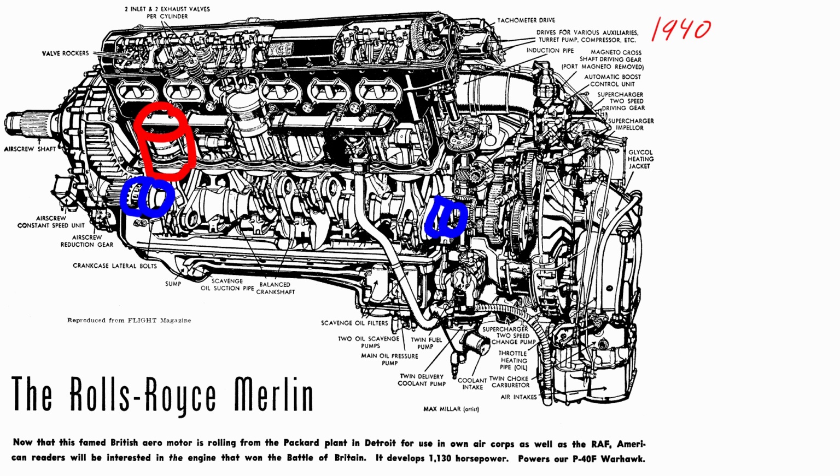And if we then look at the axis created by the bearings and the axis of the cylinder, then we want those two to be perpendicular to each other. And with dimensional tolerancing, we don't have any way to communicate that, but that became a necessity when we were going to have to build something like this.